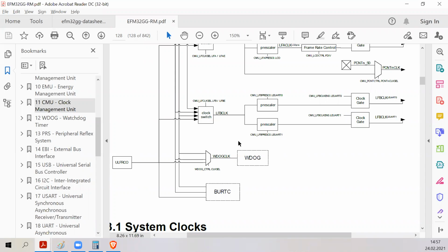So if your microcontroller has a bug and it just hangs, this watchdog timer will reset it, restart the whole program after some time. You can set it to, for example, up to several minutes, and then your microcontroller occasionally resets it. And if it hangs and it cannot go to the place where it resets it, then Watchdog will reset the whole microcontroller, and you will restart the code.